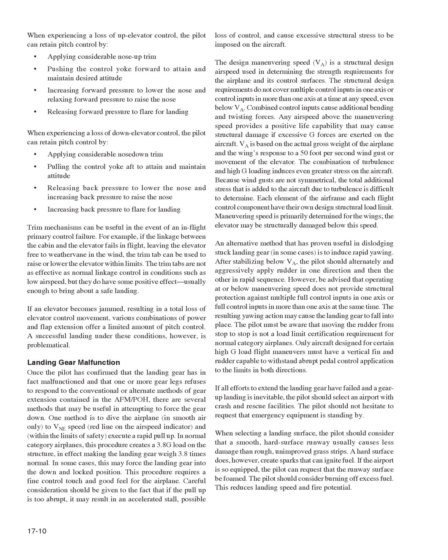If all efforts to extend the landing gear have failed and a gear-up landing is inevitable, the pilot should select an airport with crash and rescue facilities. The pilot should not hesitate to request that emergency equipment is standing by.